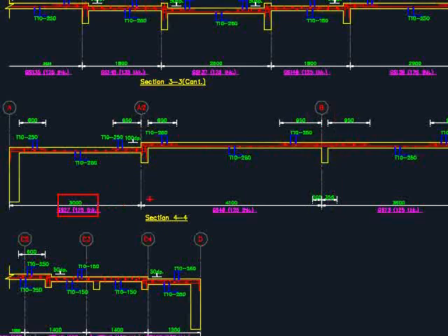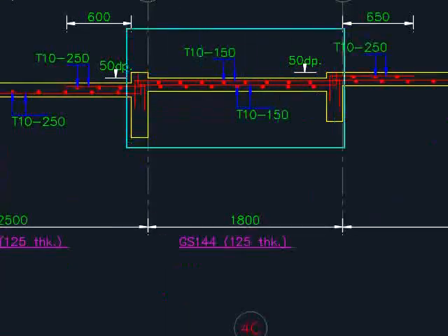There will be slab numbers. It will be in accordance with the slab numbers that you provide in the key plan. This is the one that I mentioned just now, to provide additional reinforcement bar in double layer to prevent the leakage of the water through the slabs.